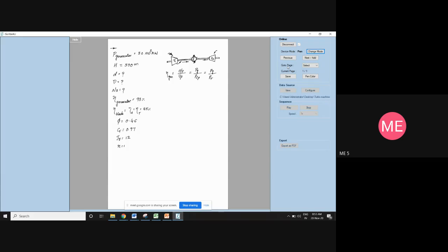From this equation, we know the generator efficiency, we know the power generated from the generator. So can you find out what the power input for the generator is? The power input for the generator is nothing but the power output from the turbine. This itself is considered as power input for the generator, right? So here I can take power from turbine is equal to power by generator divided by efficiency of the generator. Power by generator is 30 into 10 to the power of 3, divided by the efficiency of the generator, 93, so I'll take 0.93.